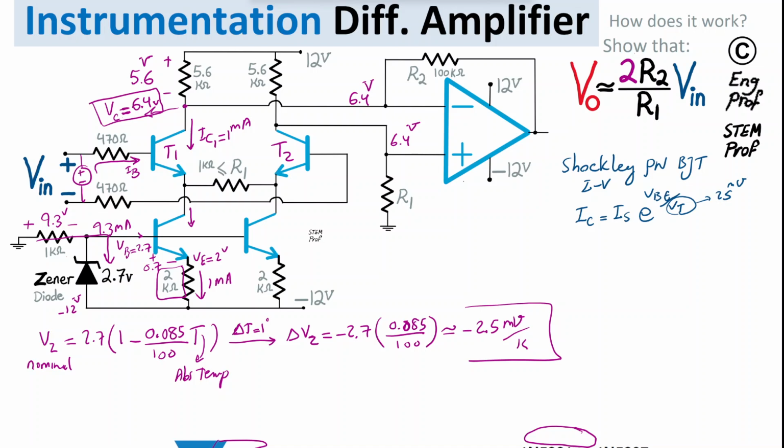So, given the matched transistors, this current IB goes into this transistor, and effectively that current is coming out as well, as a result of this applied differential voltage. So I'm going to remove this 1 milliamp because we already discussed that. So I would say I collector DC is 1 milliamp. That's what we found earlier.